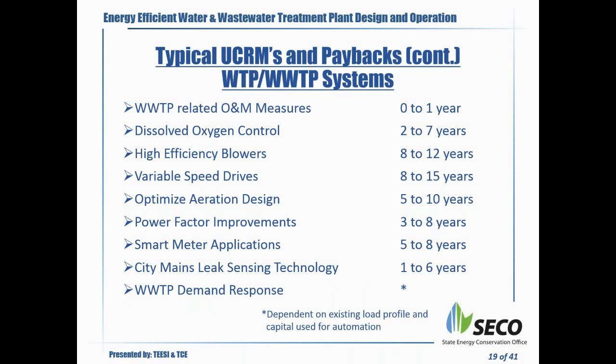High efficiency blowers have caught on and are pretty common now, 8 to 12 years. Variable speed drives application, 8 to 15 years. Optimized aeration design, we've been able to provide some recommendations anywhere from 5 to 10 years. Power factor improvements, 3 to 8 years. Smart meter applications, mostly on the water side also, anywhere from 5 to 8 years of payback. And application of leak sensing technology in the water mains and so forth, anywhere 1 to 6 years payback.